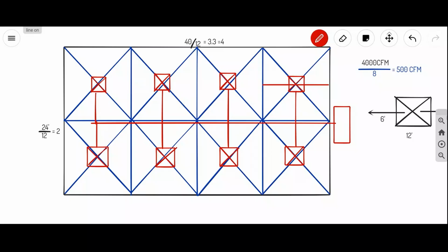After converting all these drawings into 3D layouts, whenever there is a clash between two drawings, suppose I am running a duct and there is a clash with the sewer pipes, he will suggest a change: the sewer pipe needs to be changed. When he suggests a change, we will change it, but we check whether it is affecting our calculations or not.